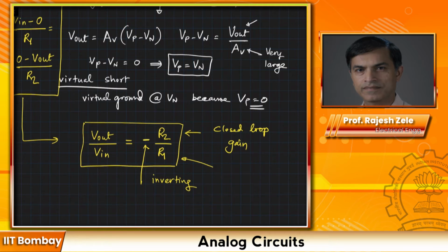However, if I draw two resistors next to each other, then both those resistors will track each other really well, almost as good as 0.1%. If you do the layout part properly, if you draw the resistors very well in an integrated circuit fashion, then you can get excellent matching between the two. As a result, R2 and R1, if they are drawn appropriately, match very well with each other.